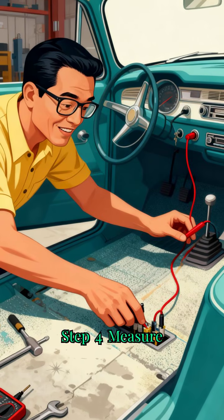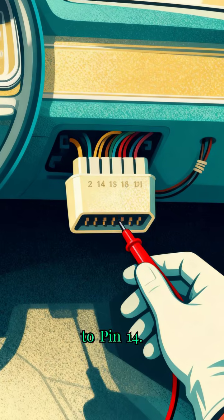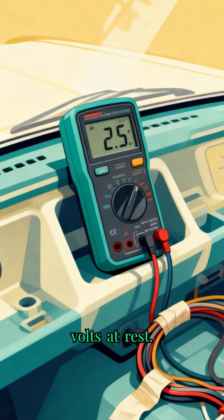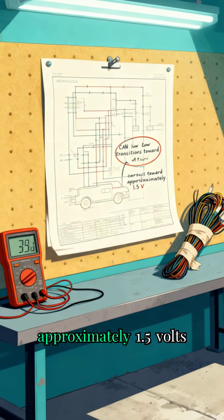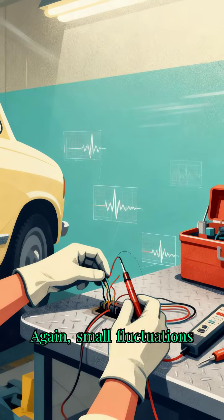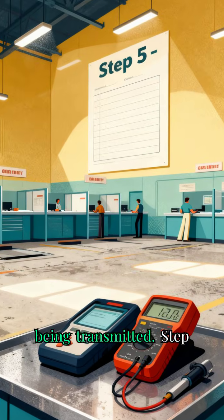Step 4. Measure CAN low. Move the red lead to pin 14. You should typically observe about 2.5 volts at rest. During communication, CAN low transitions toward approximately 1.5 volts. Again, small fluctuations are normal because messages are continuously being transmitted.